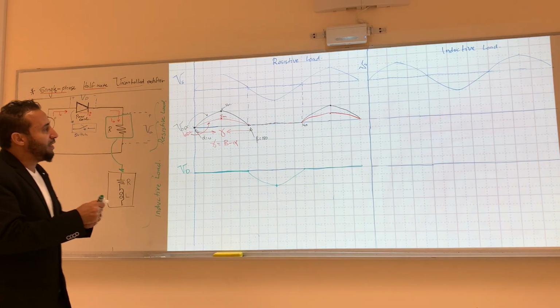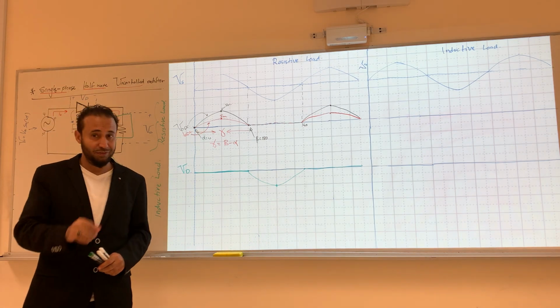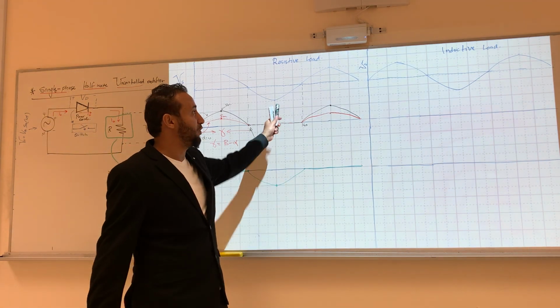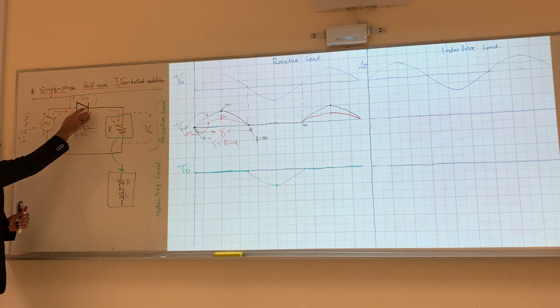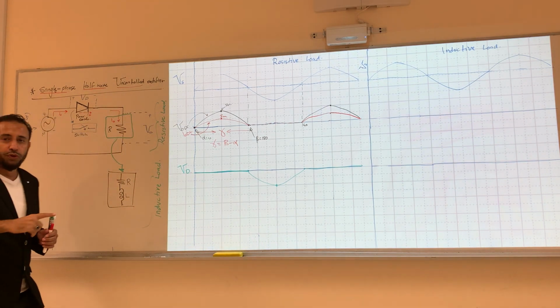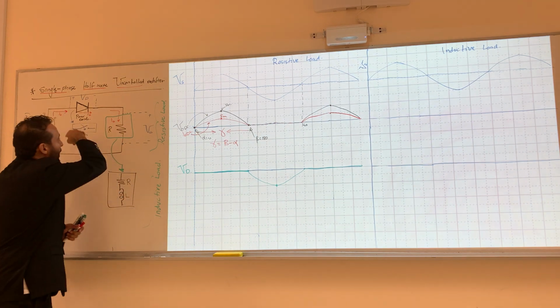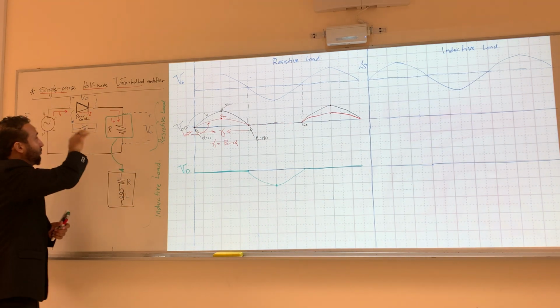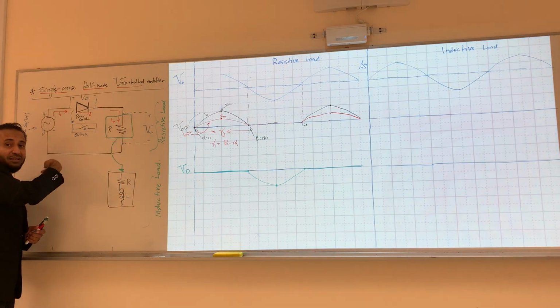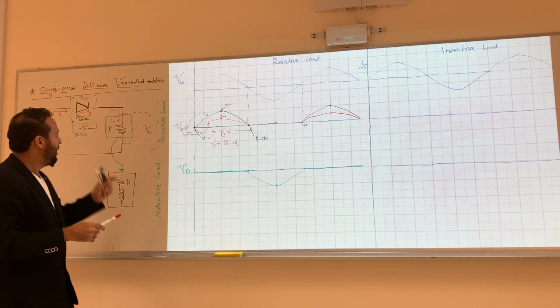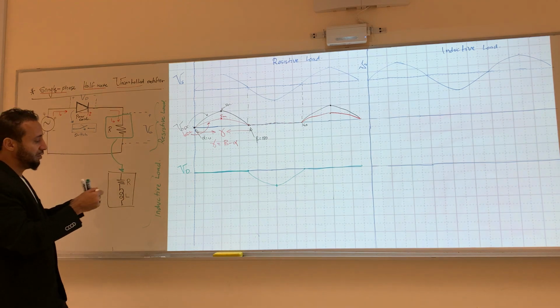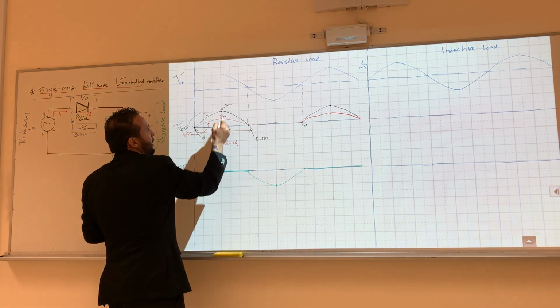Let's say, in this case, what will be the I source? This is a very good question, guys. What will be the I source in this case? Since the diode is open and closed, when it's closed, there will be current, and when it's open circuit, no current. The circuit is in series, so I source is the same as I out.